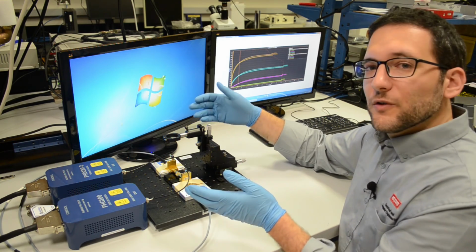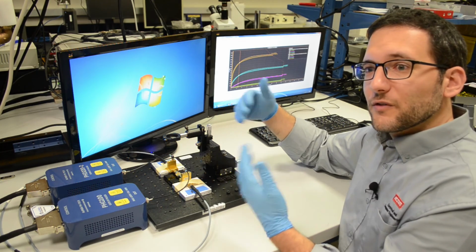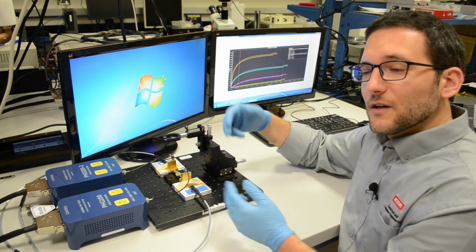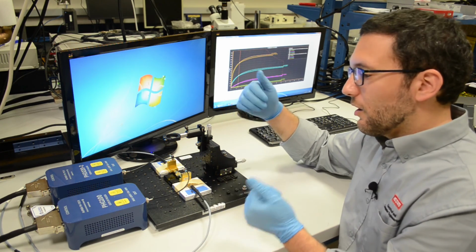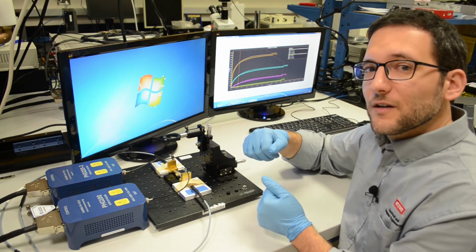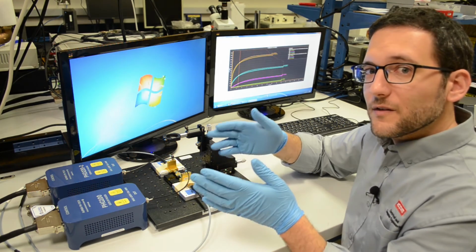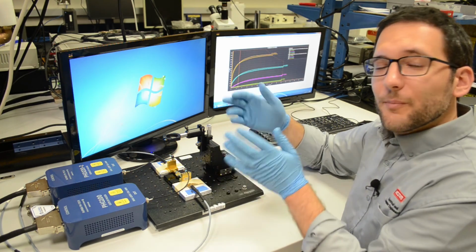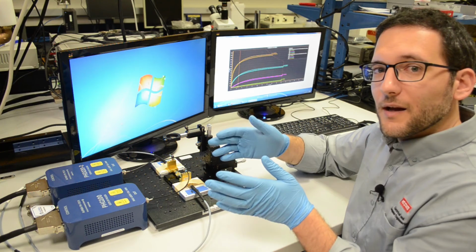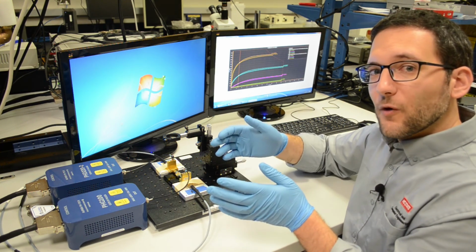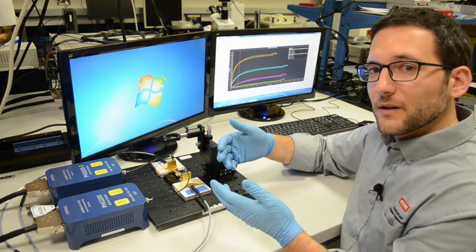So overall, what we're able to do is a variety of different measurements applying dynamic conditions, and that allows us to understand the dynamic response of these devices. Two examples of that you can normally see in papers or in product sheets are, number one, looking at the duty cycle dependence of a device. That means comparing a device in which the device is on for 1% of the time versus a device that might be on for 10% of the time. So that would mean for a fixed period, you're adjusting the pulse width that's applied. And if you see that there's a difference in the device's performance, that means that there's something going on inside that device, for example, surface traps, that might be affecting its stability.